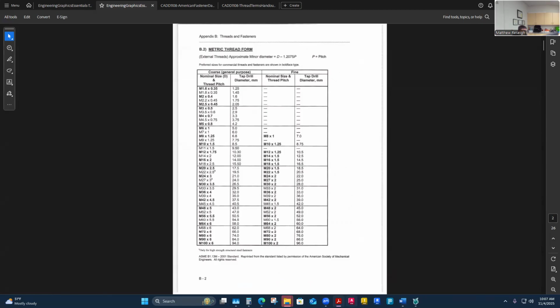That's the other thing we were talking about just off camera: in order to make holes, there are a lot of different designations of drill bits or tooling for that. They're fractional, they're numbered, they're letters, they're also metric drill bits. A machinist making fasteners and threaded holes for fasteners to go into has access to a pretty extensive catalog of bits, because there can be hundreds, if not thousands, of different thread fastener relationships, and they have to have the drill bits to do those, and not just one that's close enough. They need the actual one.